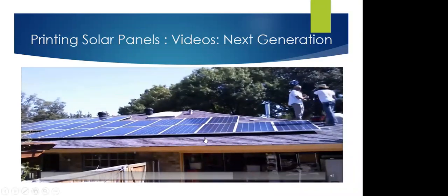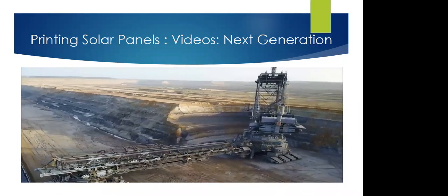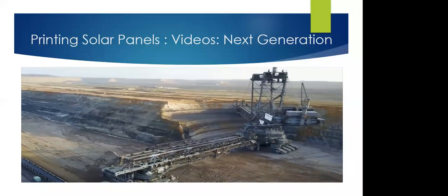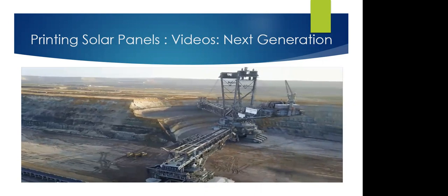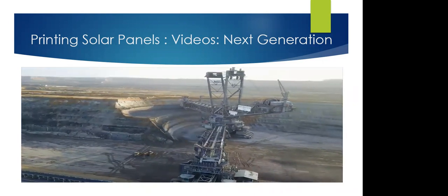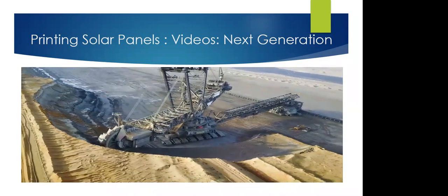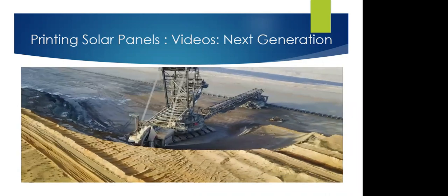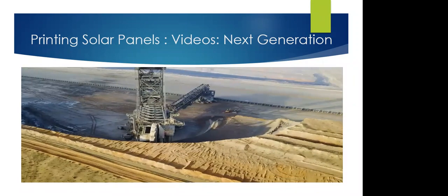A balance must also be struck between the efficiency of the device and the environmental impact of its manufacture. The most efficient thin film solar cells include toxic or rare materials such as cadmium and lead, as well as hazardous organic solvents. Indium, another rare element, is a common ingredient in transparent conductive films of PV devices. Its use is expected to rise over the coming decades. However, depleted mineral deposits and low rates of recycling threaten to exhaust indium stocks before the end of the century.